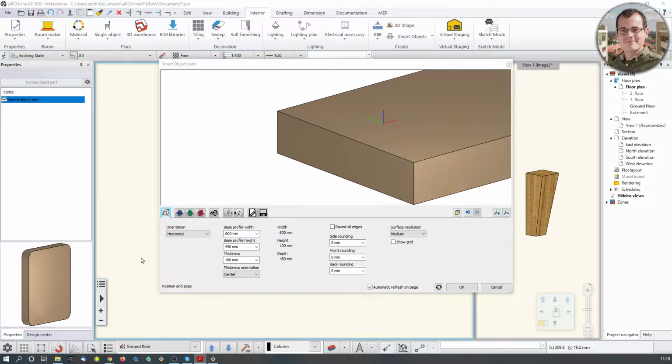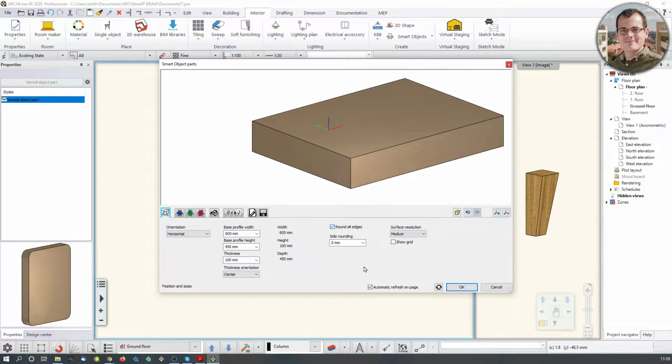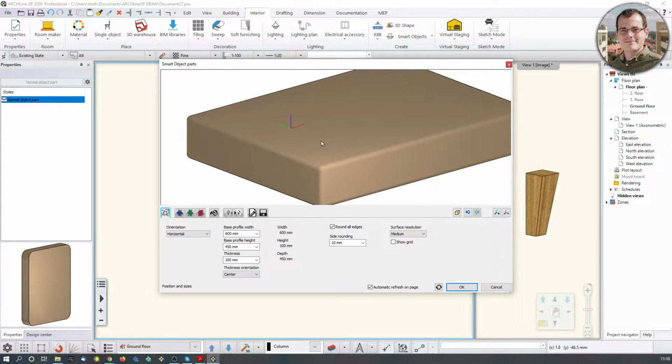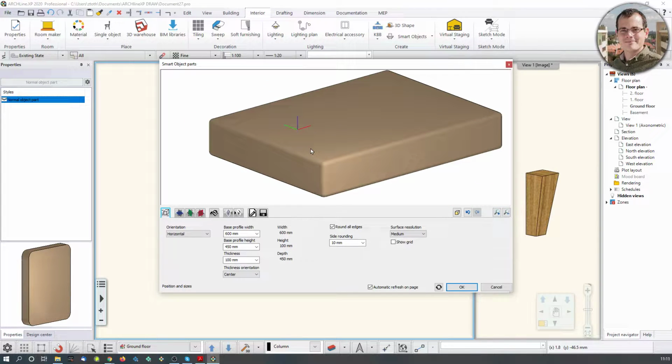Well, there's a tool that we call round off the edges, and I click on that and I see that the rounding value should be 10 millimeters, like that. So if I do that, the software would sort of fillet the edges. It's like a milling machine, right? But here's a quick warning for you. 2 things to consider here. One, you can define how high you want the surface resolution to be, so you can go all the way to the lower end or higher end.